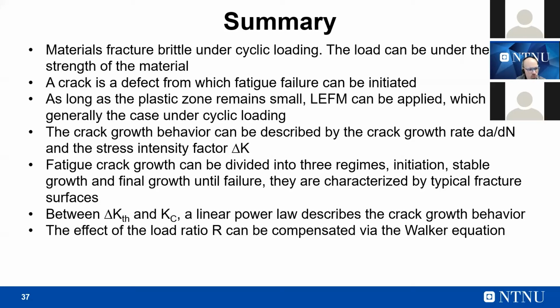I have introduced to you the plastic effect that we always have if we have a crack, but we have to consider it locally because usually this is very local and concentrated only in the vicinity of the crack. Outside this region we can use linear elastic fracture mechanics, and we have powerful tools like the Paris curve and, for example, the Walker equation to estimate how the crack grows and what the remaining life of our component is if we have an initial crack that we can detect and measure inside our component.